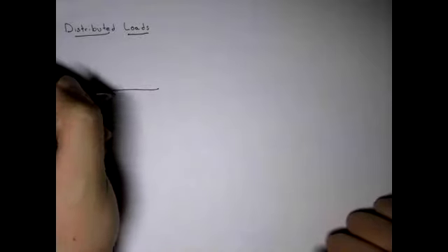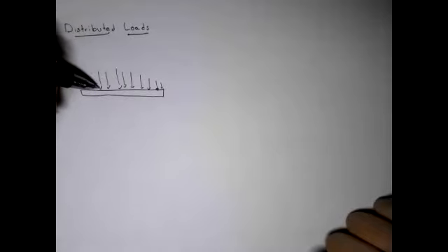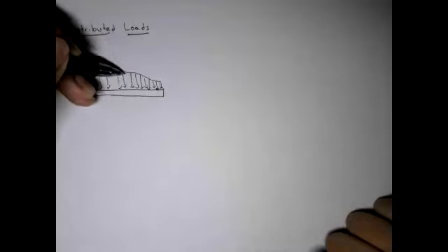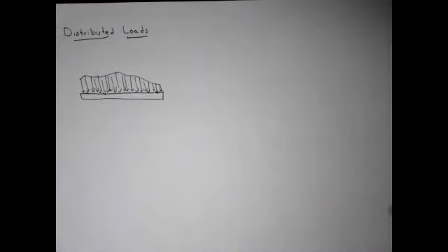When I say the word distributed load, what I essentially mean is a force that is distributed over an area or a length. Now in this class, we can distribute the force over a length. In other words, instead of one force acting at one point, I can have a force acting at every single point of a length. So essentially what I'm looking at is a continuous force that acts at every single point of a length. So how do we quantify this?